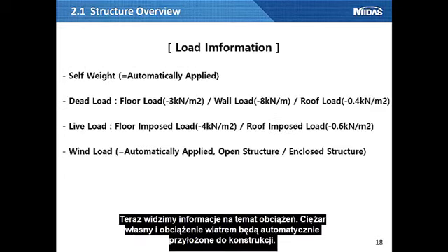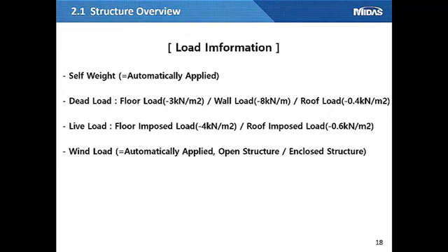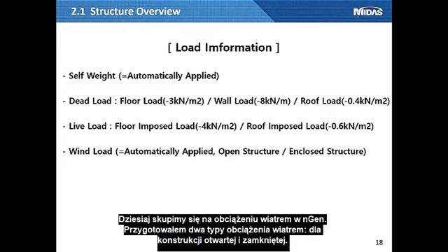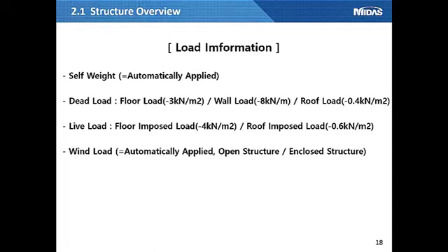The loading details are shown. Self-weight of frames and wind load are automatically applied on the structure. Dead and imposed loads are mostly applied as floor load type. Today, I will emphasize the wind load calculation in nGen. So I prepared 2 types of applying wind load for the open structure type and the enclosed structure type.